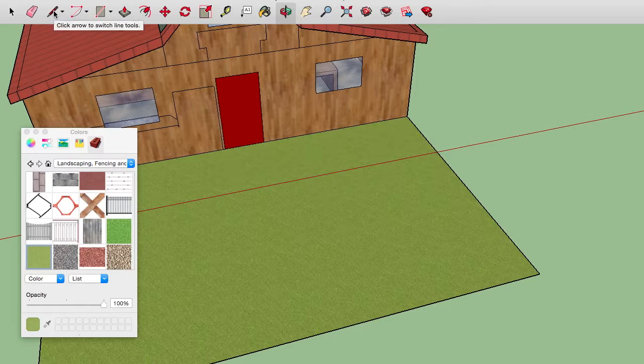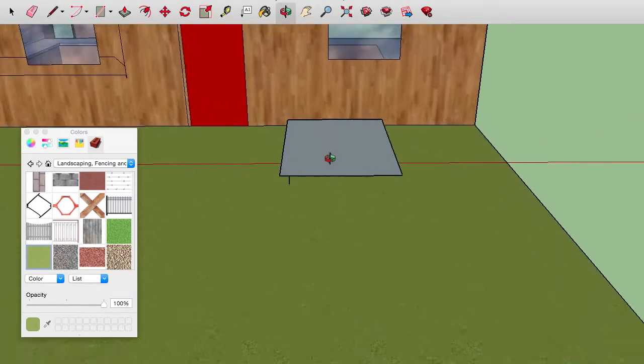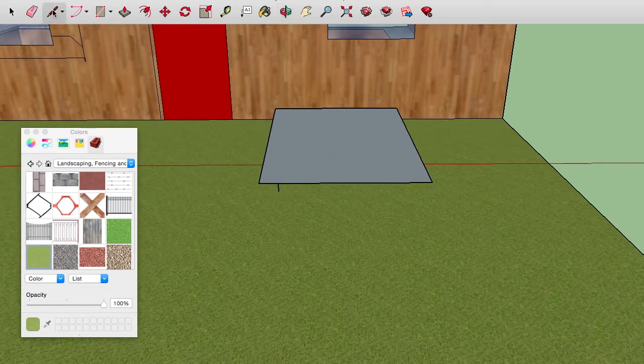Again, everything you do in Google Sketchup, you're doing completely raw, and you have to create it yourself. So right now I'm going to show you how to draw my idea of a picnic table really quick. You see I made that 4 feet, 6 feet, and all you do is you kind of move the line in that angle, and then you type in the number with the apostrophe marks, and then hit enter, and it'll go in there, or quotation marks for inches.